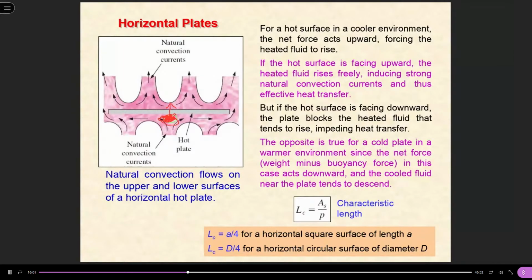Imagine this is a balloon. I think I illustrated this before. A helium balloon, a balloon that is lighter than air, if you let it go, just flies up. In a room, it will stick to the ceiling and move no more, right? But if this balloon is heated, then it goes upward, and then some cold air comes in to replace it, is warmed up again, then goes upward again. Therefore, a hot surface facing upward will have a continuous, stronger airflow than when it faces down.